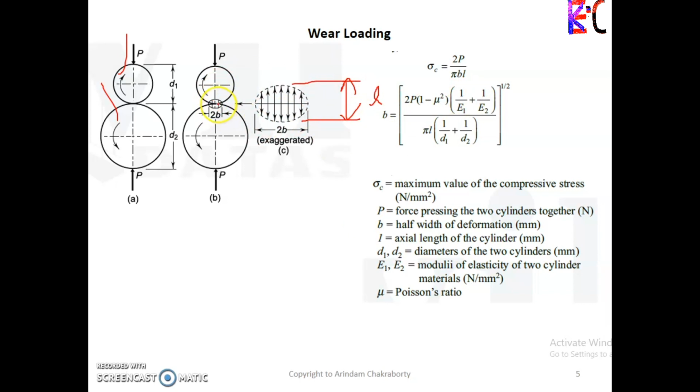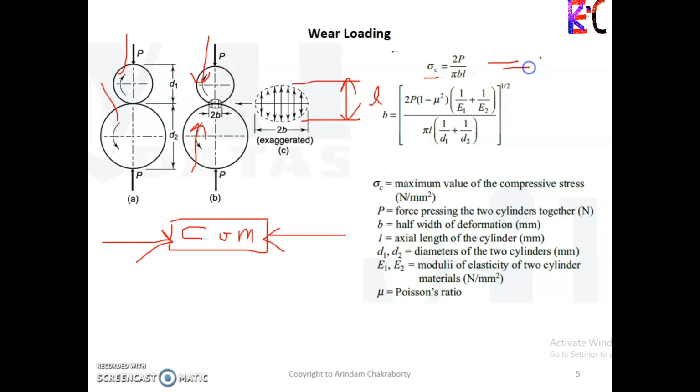Now since it is applying force over here, something like this occurs, as we know. Can anyone tell me what type of force it is? It's a compressive force, so it will be sigma C. What do you know about sigma C? Sigma C equals force by area. Where did I get this from? Now I know what force is, force is this one. What is area? So let us calculate the area.